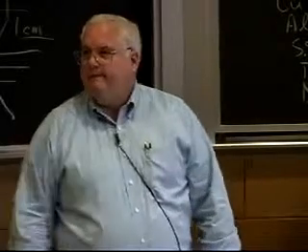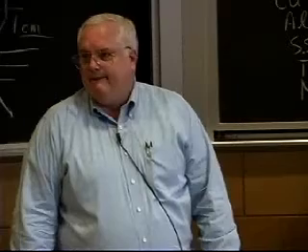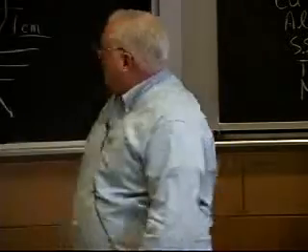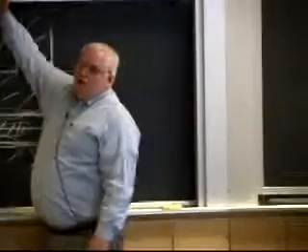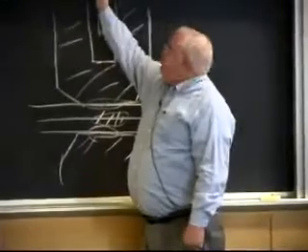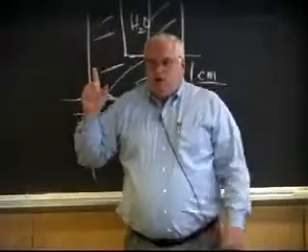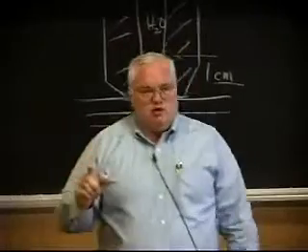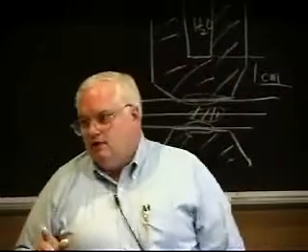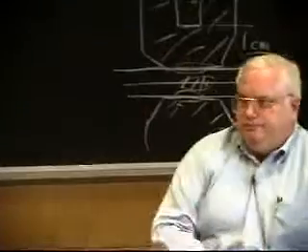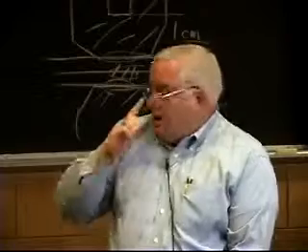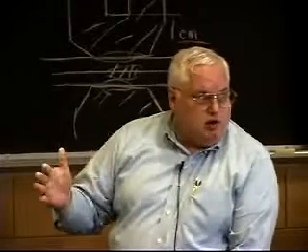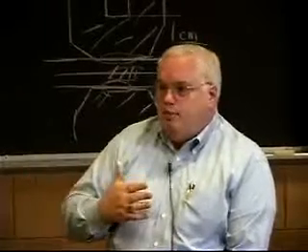I have a question. Actually, I have 2 questions. So when is the Fourier number shortcut applicable? It's applicable when you want to know, am I just superficially heating or am I saturated? When you really want to know something precise, if you run the Fourier number and it's anywhere close to 1, let's say it's 1/2 or it's 2, you usually have to go ahead and solve the whole problem if you really want to know some details. But in most cases, 95% of the time, all you want to know is, did I saturate my material with heat or did I not?